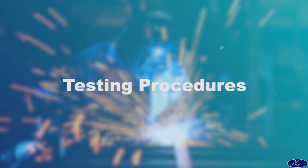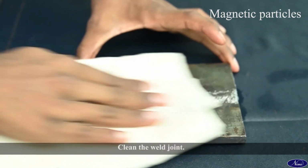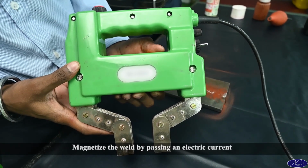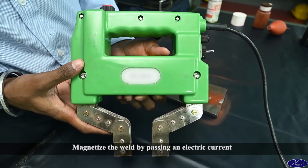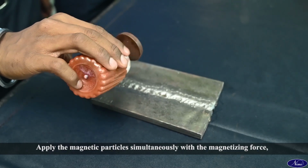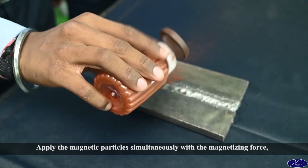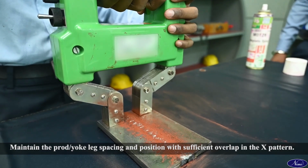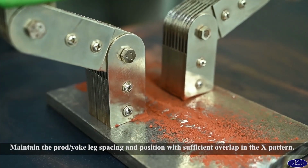Testing procedure. Clean the weld joint. Magnetize the weld by passing an electric current. Apply the magnetic particles simultaneously with the magnetizing force. Maintain the prod or yoke leg spacing and position with sufficient overlap in the X pattern.